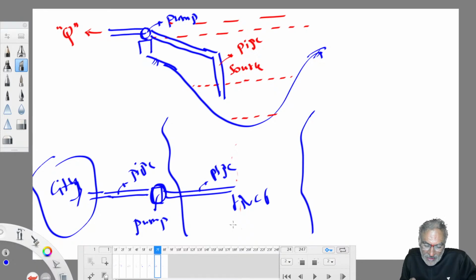Understood? If the water level highly fluctuates, in summer the water level depresses to a very low level. When it goes so low, again you can't collect water properly. Water is not available to this pump. You can't extend this pipe length either. Even if you extend it, nothing happens, because this is a suction pipe. Suction has a limited capacity. It can lift water only to a limited height. Beyond that height, nothing happens. Therefore, within that suction capacity, we have to install a pipe inside the source. For conveyance purposes, you can convey any distance. That is not that difficult.